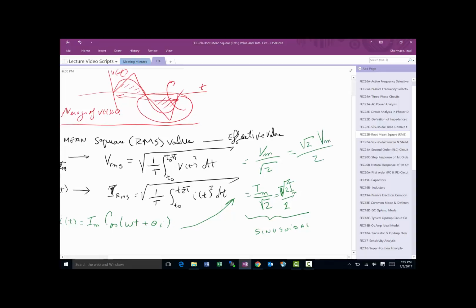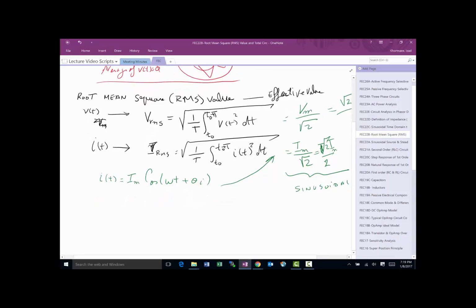Actually, most of the power companies in the United States say the voltage they deliver to your house, V, is equal to 120 or 110, something like that. Let's say 110. What they're really telling you is this value is the RMS value. Which is roughly, if they were giving you a DC, if they took the negative lobe and brought it to the positive side on their sinusoidal signal and then smushed it down so it was an even flow, it would be 110 volts.